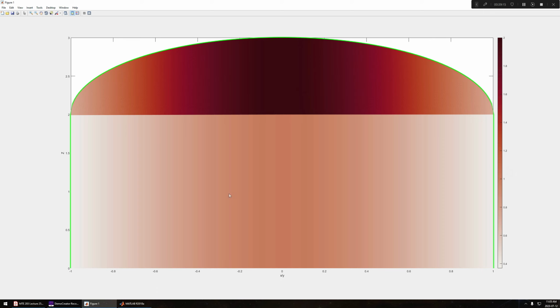All right? And generally, rockets are stable if, let me see, I can draw on here. Yeah, rockets are stable if my center of mass is higher up than my center of, down here, another center that is the center of, if you will, aerodynamics.